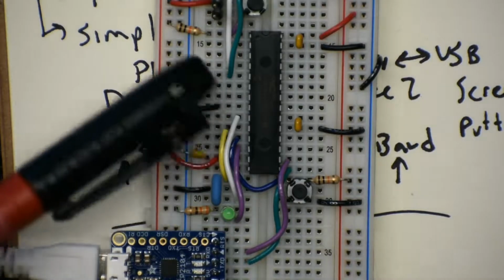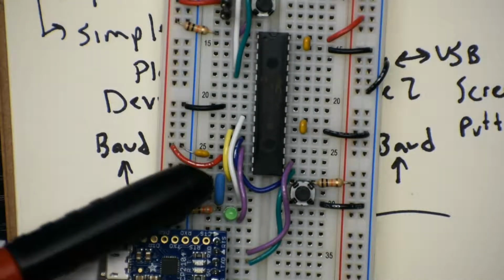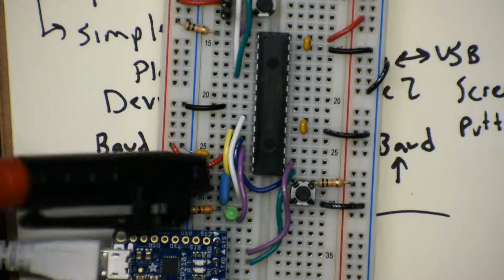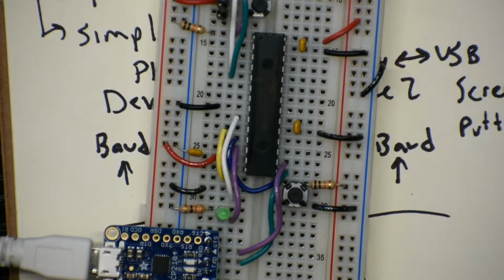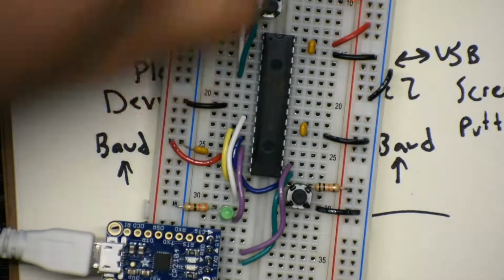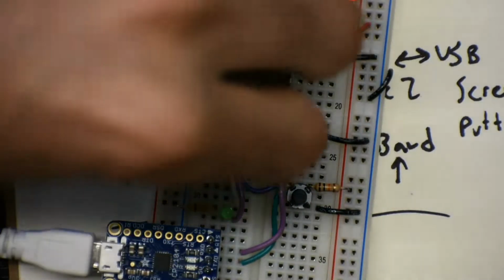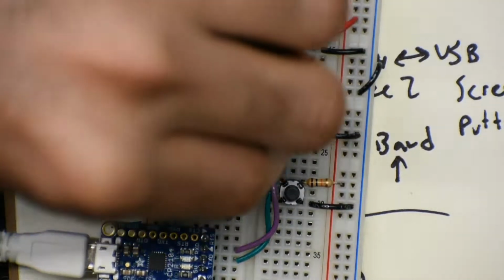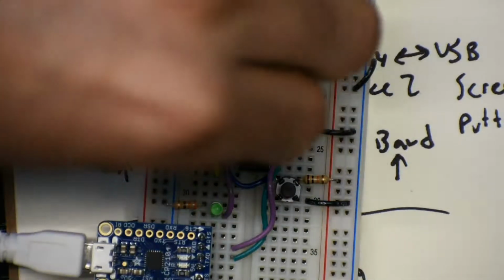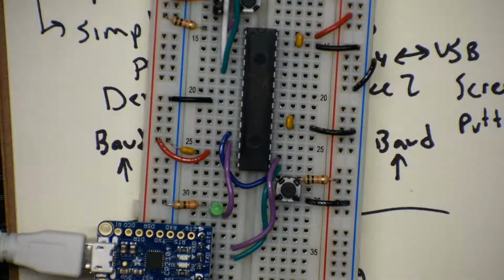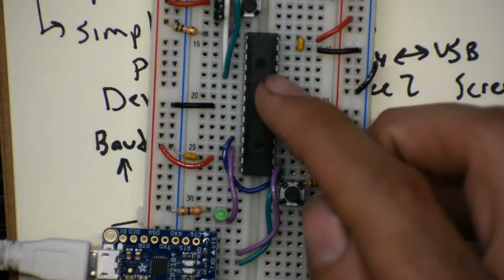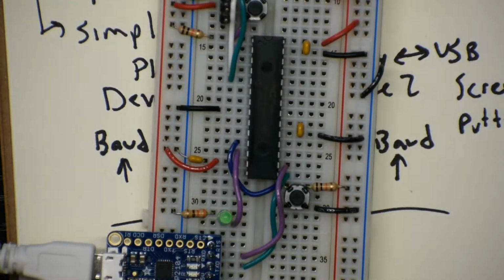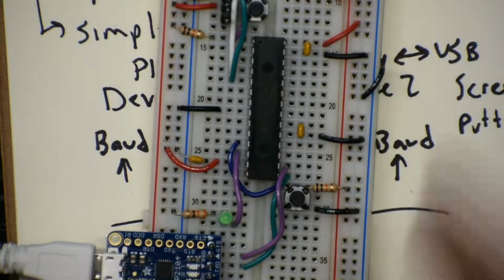And one thing we did here is we have the PIC running off an 8 megahertz external crystal resonator, this little blue chip. I'm going to yank that, and we're going to get 2 more pins back available to do other things. And instead, we're still going to get the PIC to run at the same speed that we're running at. So we're running at 48 megahertz using the PLL. We're going to use the internal oscillator of the PIC that also runs at 8 megahertz and PLL to 48 megahertz without the external crystal resonator.